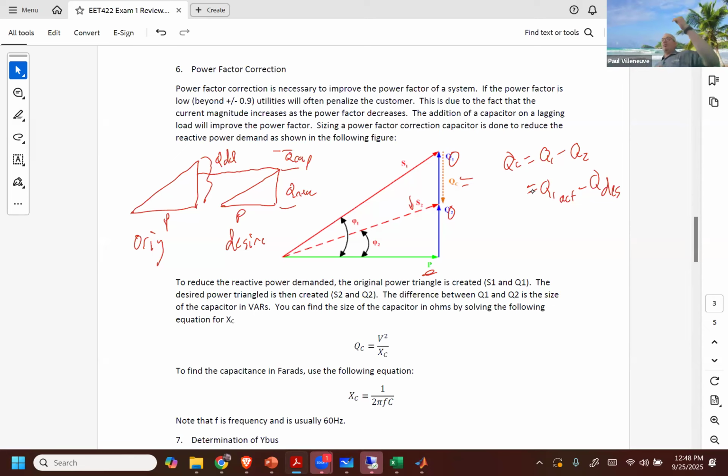And the reason why this works is when you draw a power triangle that typically has a lagging power factor, the lagging power factor is going to be an inductive type circuit, right? ELI says it's a lagging power factor. So if we want to improve the power factor, we have to add some leading capability in there, which is what the capacitor does for us, right? It is a leading power factor, so it's going to give us a little more. And there's essentially no charge to improve the power factor. I mean, obviously, we have to pay and purchase a system that has capacitors and install it out there. But once it's there, it doesn't consume any real power effectively. So we can put a capacitor on there for almost next to nothing, and we can save ourselves quite a bit of money on the machine.